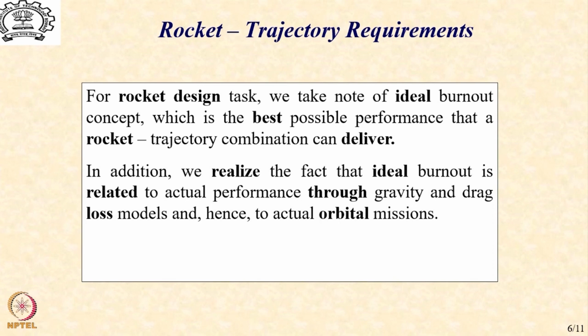Of course, it is not very difficult to see the connection that the ideal burnout is also related to the actual performance, which is dependent on the loss due to gravity and the drag. So, if we can make a reasonable estimate of these losses, we actually will get the desired actual performance against the designed ideal performance.